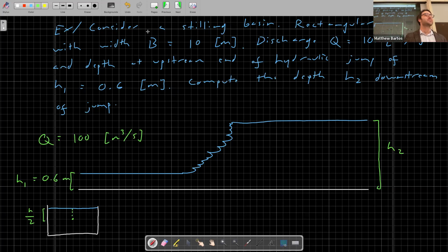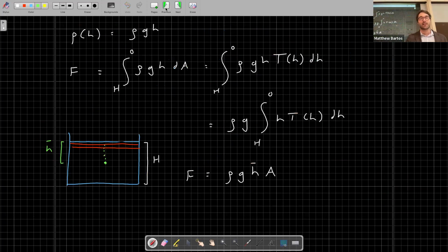Are there other questions about this? So I hear some murmurs. This centroid that I'm talking about here is different from the centroid of the pressure triangle. If you think back to statics, if you're applying not a momentum balance, but a balance of moments, that's when you'll use the centroid of the pressure distribution, which for a triangle will be a third up from the base of the triangle. This here is for computing the centroid of the channel itself, and that comes from this integral here.